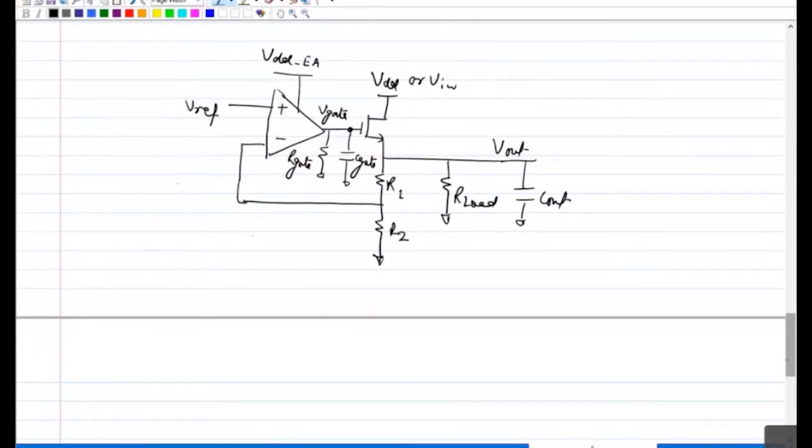What is the impedance looking into the output node? Very small, as the source of the 1/gm. But what about the feedback? Yeah, so that will be divided by 1 plus Aβ, as we saw in the other case for closed loop.